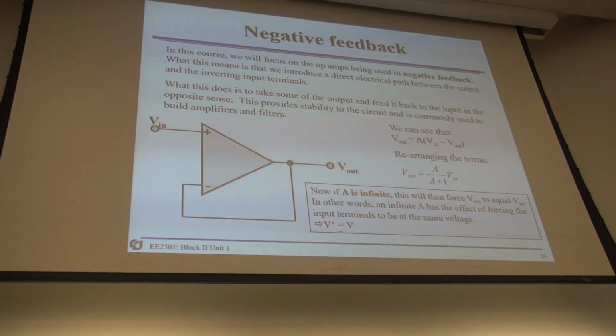So, voltage follower. That's how to make 0.5 times 0.5 equals 0.25. You need to insert this in between these two voltage dividers with finite resistance. That's why I gave you the quiz, and you know what the answer is today. It is the same as you said wrongly last time, right? But there's a fundamental concept in here. It's about input resistance, output resistance, the cascading of this amplification.